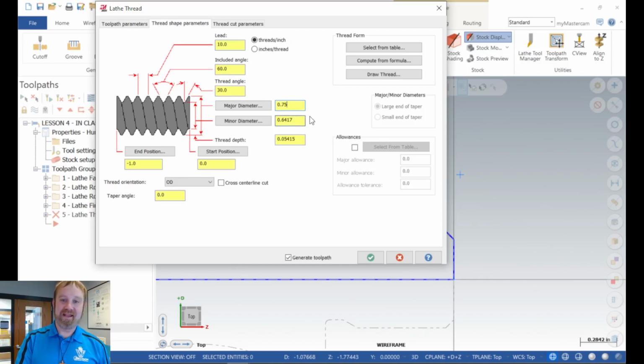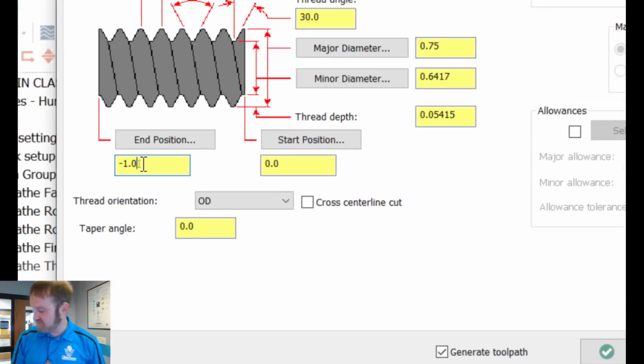So anyhow, like I said, these things I leave where they're at. Now, in position for the tool, right now it's going back to 1 inch, which is where the shoulder is. Let's put 5 thou back on that to keep it off that shoulder. We're going to leave it 5 thou shoulder to shoulder. That way it goes all the way into the relief groove.